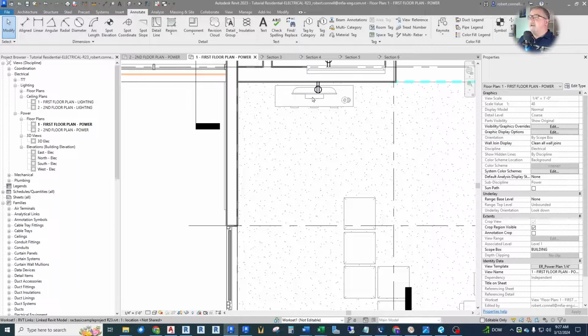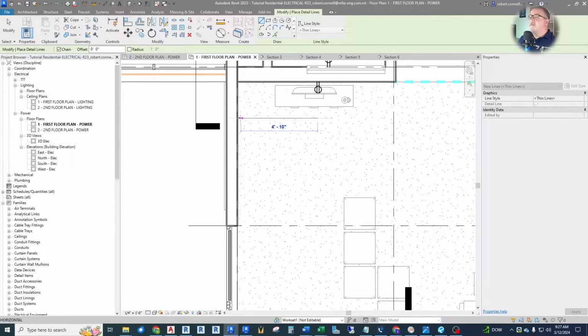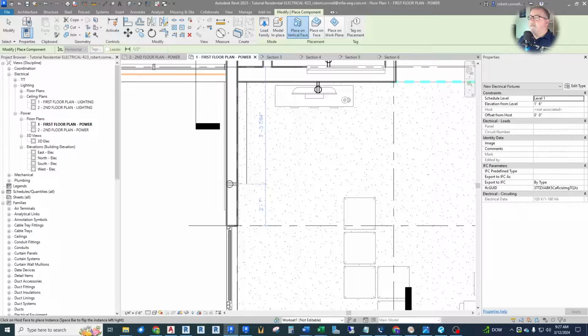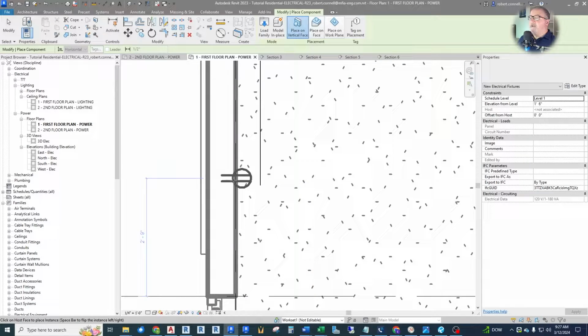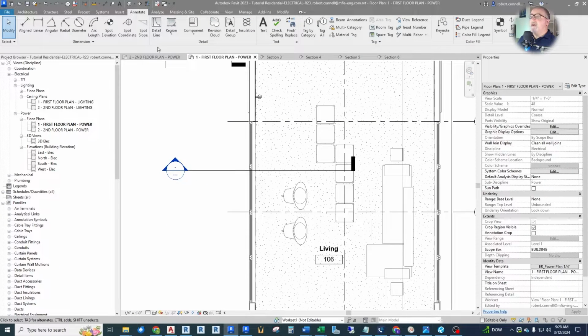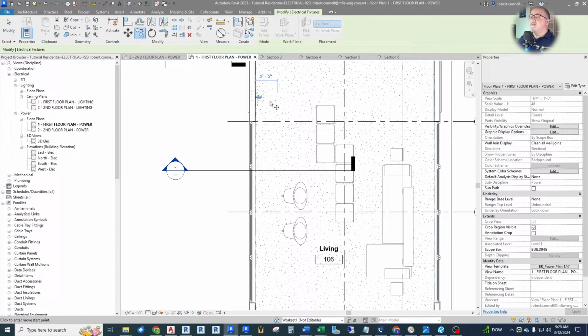So we've got that, and we have 5 more feet, so we can go 7, but let's keep it a little bit short. Put that there. Now this is again where we have a grid line in the way of our wall. So hover over the grid line, hit tab. Now we are on the wall surface. And we want to copy this not more than 12 feet away.